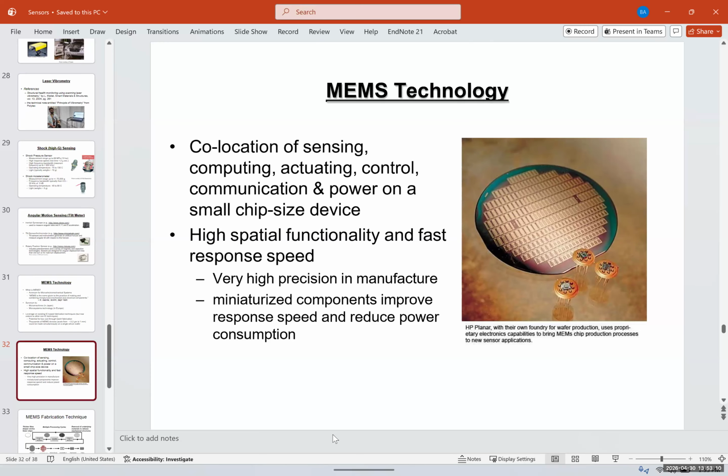But basically, this is a wafer, this big disk, and a wafer is made out of 99.999% pure silicon. And we use different techniques like lithography to carve into that, and then we fill it with N and P dopants, so we create PN junctions and so on. So we can create diodes and transistors and ICs, which are integrated circuits. We use the same principles, but we do the carving in a way that creates sensors.